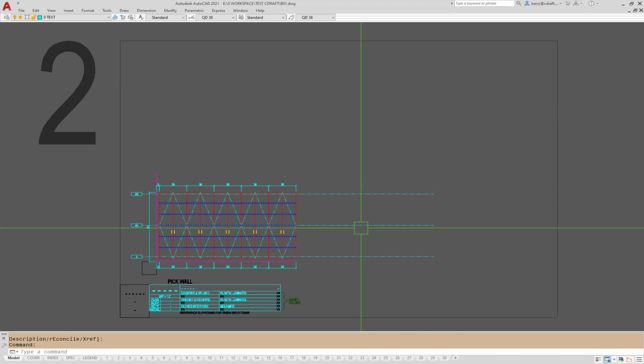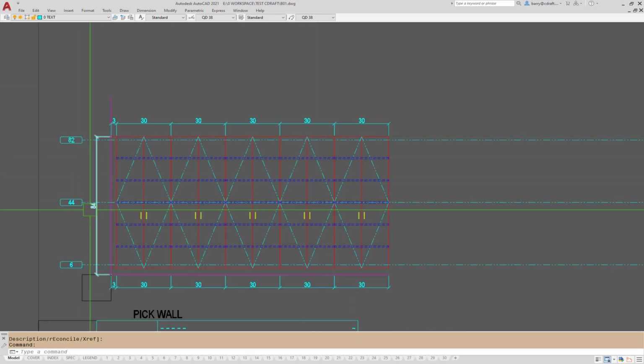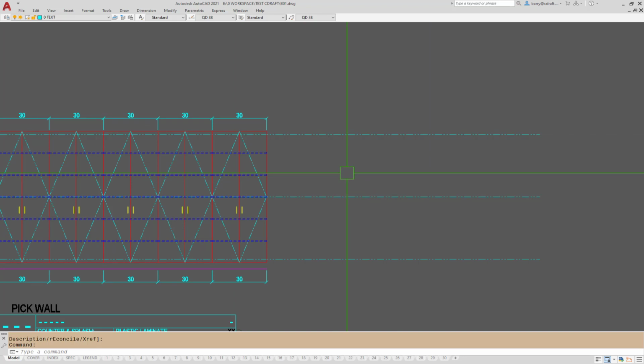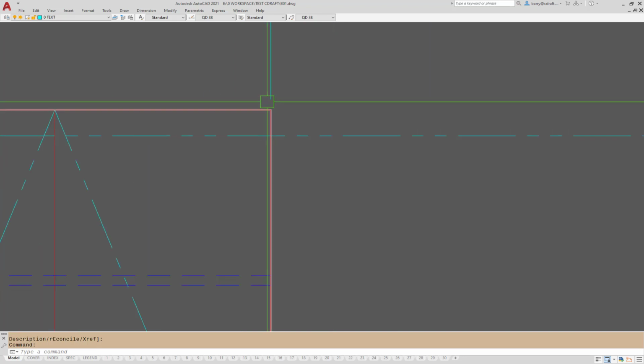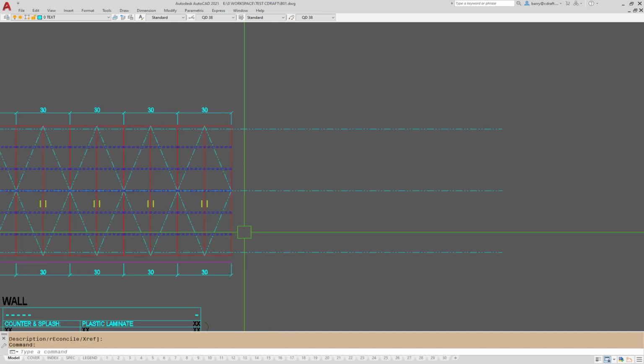When we ran this command, it set our countertop variable back to 0, but this 84 inches also applies to wall cabinets. So let me show you what just happened here. We've shifted now our insertion point to right here. So let's do a wall cabinet, W2.